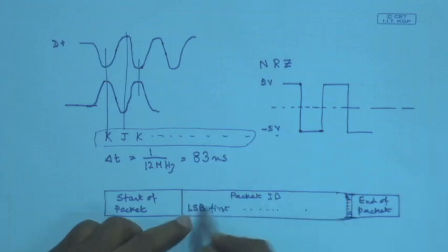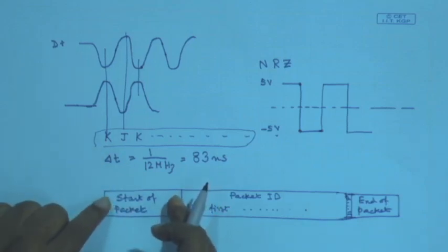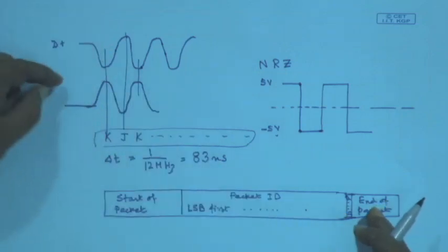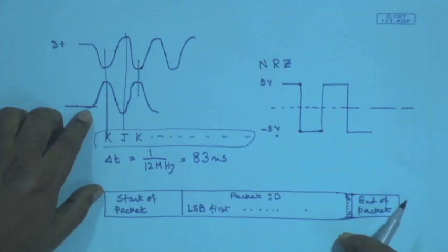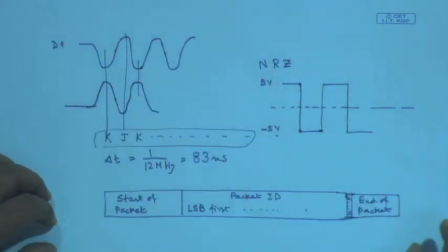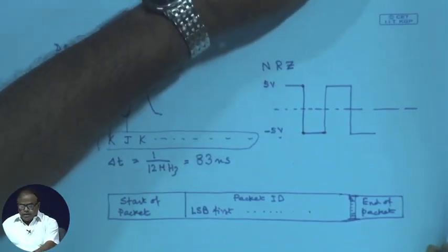That serial bit will have to be encoded with the start packet and end packet, and also we have to transmit it using this non-return to 0 protocol, through a differential pair, and vice versa. But the thing is much more complicated, so we are not going into details, but you have got converters available for that.